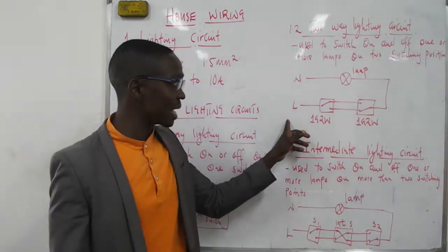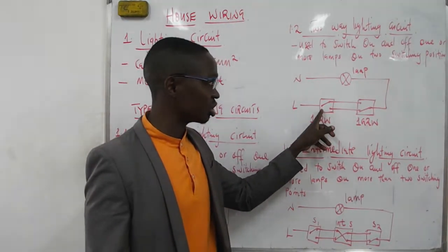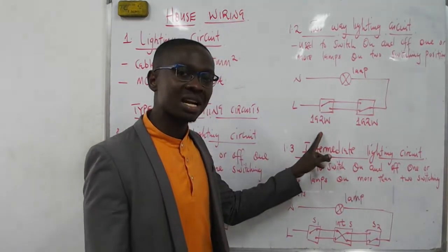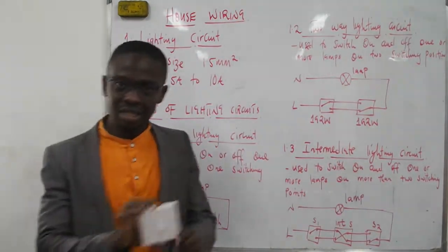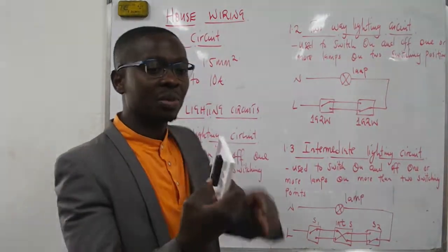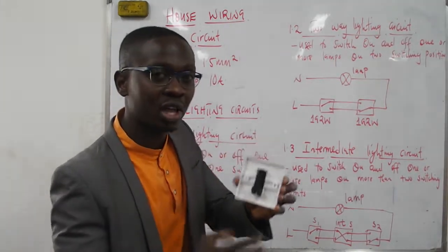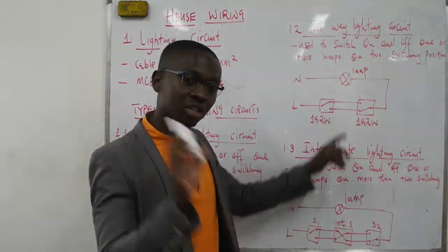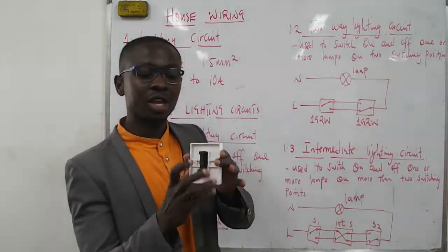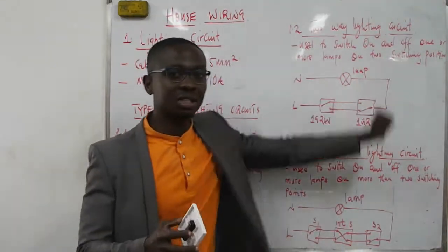So from supply, it enters the inlet or the common of one switch. Then that switch has two outlets. These switches are called one-gang two-way. They look like this. In front, it's just a gang. A gang is this thing we press. But behind, it has three terminals: the terminal for the input and two terminals for the outputs. So you've got a switch of this kind, now two of them. From the common or the input, you supply, and the other one is where you feed the load.